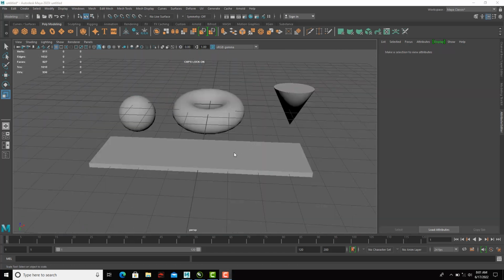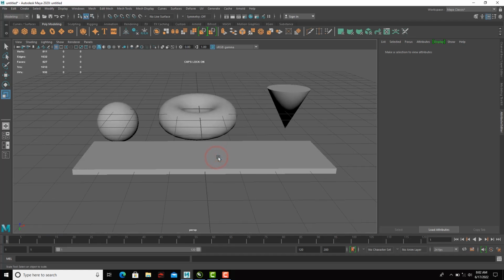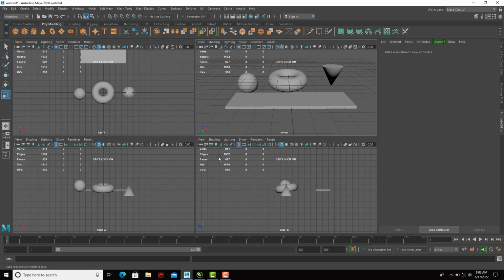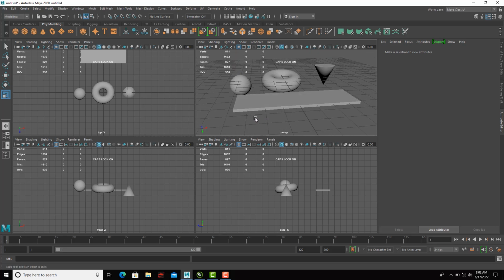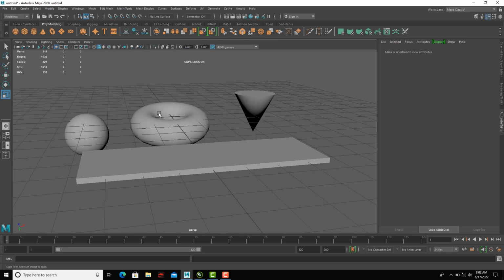You can zoom and rotate, and we can also move. All right. I'm sorry guys, before we move to camera navigation, I want to quickly show you guys something. If you mistakenly hit your spacebar, it's going to split your screen into four. Later, I'm going to make a tutorial about this to explain this further. The reason why I'm showing you guys is because if you mistakenly hit your spacebar and see something like this, don't panic. All you need to do is move your cursor to any of these views and hit the same spacebar. It's going to maximize it.